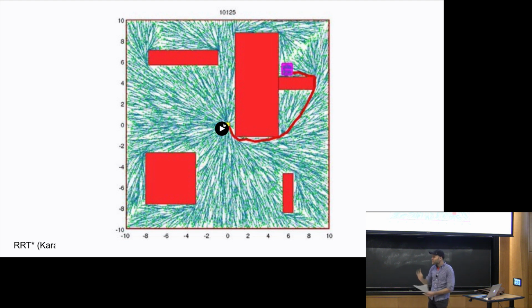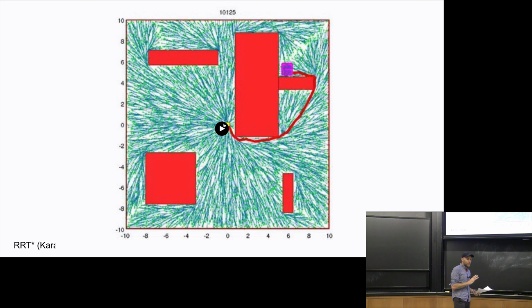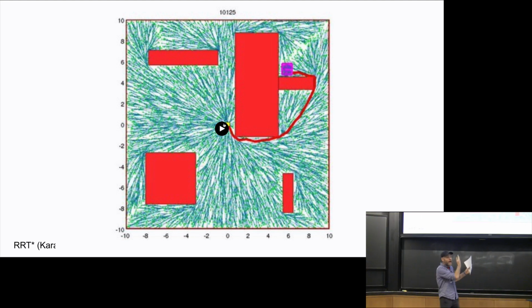But the reason that these are my straw men, I actually think that's a good idea, and you could try that. But there's something that's not quite right about this, or there's something that doesn't, I think, solve the fundamental problem. And it's rooted in the fact that the vocabulary here is trajectories in state space. Okay? It's the fact that we're thinking about lots and lots and lots of single solutions. And there's really no good vocabulary. In this vocabulary, there's really no way to talk about uncertainty, disturbances, robustness along single paths. These are single solutions of the nominal system, right?